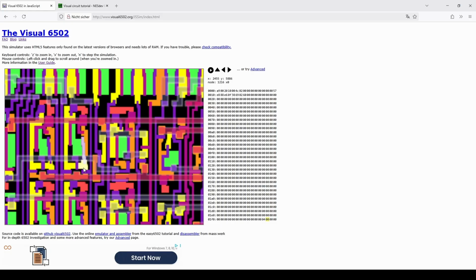So this yellow area is connected electrically to this silicon, which means that it's controlling this as a gate. And because it's yellow, because it's effectively 0, this gate is blocking, which means that whatever is here, this orange stuff, there is current here too, and it would like to go to ground, but it can't because this silicon is blocking it. And the black stuff is basically the insulator.